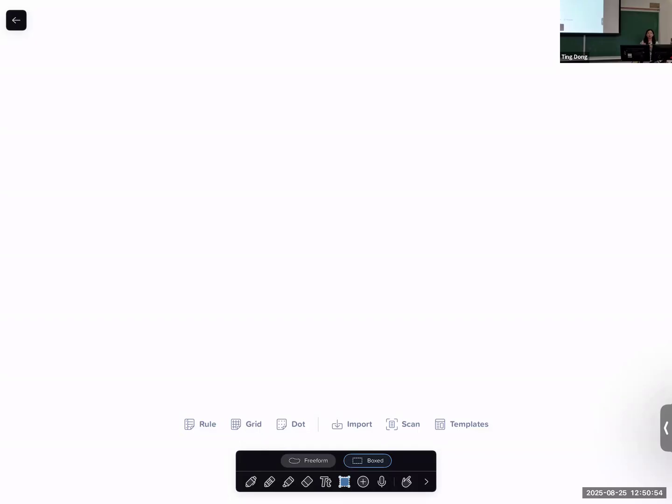So in the last class, I talked about the topic of the semester in general. We learned the bar element, we learned the beam element, we learned the 2D CST, AST, Q4, Q8. The basic idea is that for a real-life structure, for example, this table or anything you are designing in your senior design class, we cannot really solve it using our basic model from mechanics of a single bar, a single shaft, or a single beam. So what we need to do is discretize a complicated real-life structure into small elements. And for each element, we can use what we learn from mechanics of materials to solve those problems.